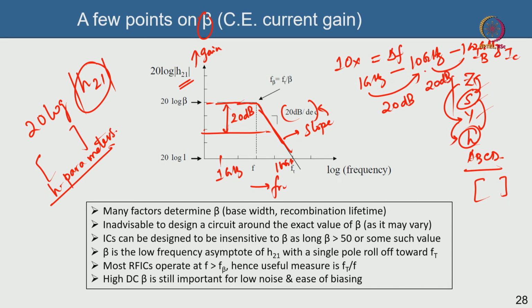That is ideal. Realistically, certain components can make it slightly more or less, but 20 dB per decade is the standard, it is how it falls. And in control theory, of course, you can say that it has hit a pole. If you remember your undergrad electrical and controls classes, you have poles and zeros. So, we say that it has hit a pole in the transfer function, and so it has started falling off at a 20 dB per decade slope. What is the physical underlying understanding?